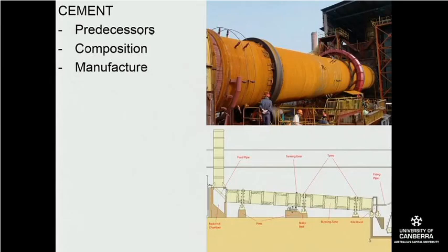Now, it comes out in clinker form, which means it's kind of little nuggets of cement, which are then ground into a powder and mixed with gypsum powder, which is that white powder that you use for walls in board form most of the time nowadays, like probably what the ceiling is. And the purpose of the gypsum powder is that without gypsum, the cement would set too quickly. So the gypsum is a retardant. It slows down the setting qualities of it. So this combination is called Portland cement, which is a contemporary form of cement.